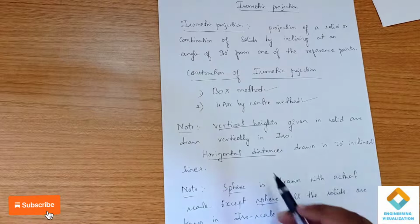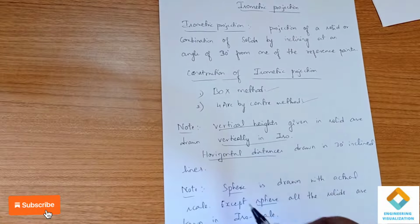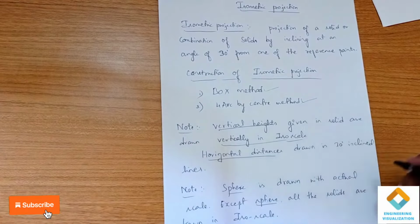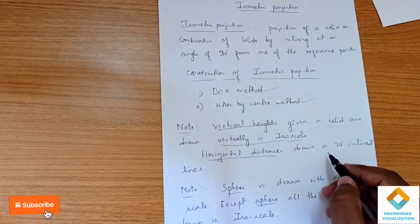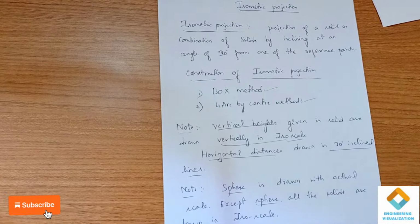Okay, so vertical heights given in a solid will be drawn vertically in the isoscale. There is no change if the vertical heights are given. That will be drawn vertically in the isoscale. But if any of the distances are given horizontally, the horizontal distances are drawn along the 30 degree inclined lines. In the isoscale there are 30 degree inclined lines to the right, and along those lines we are going to draw the horizontal distances.